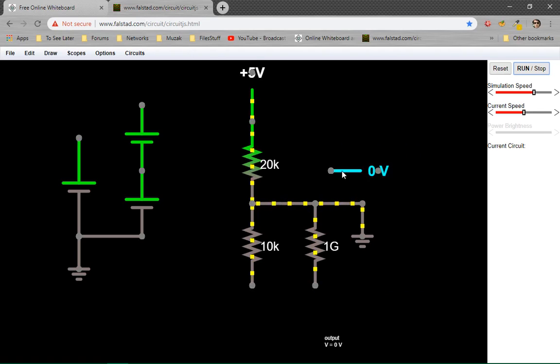With voltages, one thing you have to realize is that voltages are relative. You always need 2 terminals to make a voltage sensible. And the place where everything is connected in common, because it's what we are considering 0 volts, will be where we use this symbol.